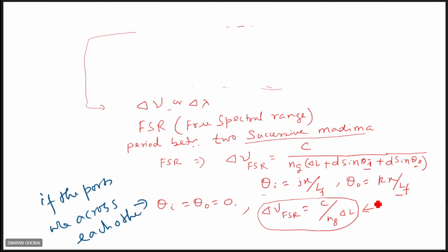This is also used to characterize arrayed waveguide gratings. These gratings can be used for multiplexers, demultiplexers, routers, etc. They have wide applications. Basically it is based on a Mach-Zehnder type interferometer. In a Mach-Zehnder there are only two waveguides, but here an array of waveguides is used, as in arrayed waveguide gratings.